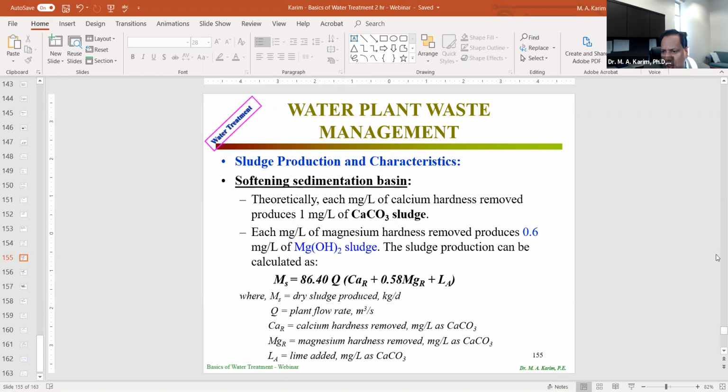EPA, there is a question here. Is EPA pushing for non-chlorine type disinfection technology? Yes, it is for the wastewater. Definitely non-chlorine is more prevalent and more useful. But for the drinking water, you can do it, but still chlorine is required because the chlorine has to be in the water as a persistent residual. If cross-connection, cross-contamination happens, that residual chlorine in the water before it goes to the individual houses can kill it and still be safe. So that's the only difference between these two. Yes, EPA non-chlorine type disinfectant is better for the wastewater, but not for the drinking water.